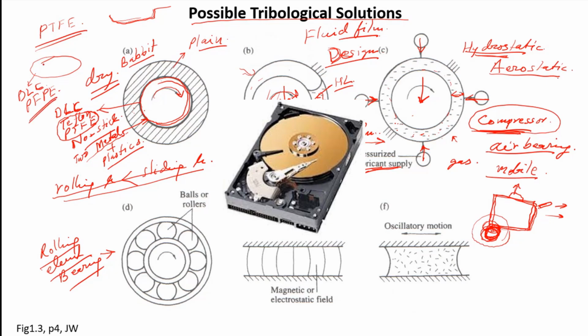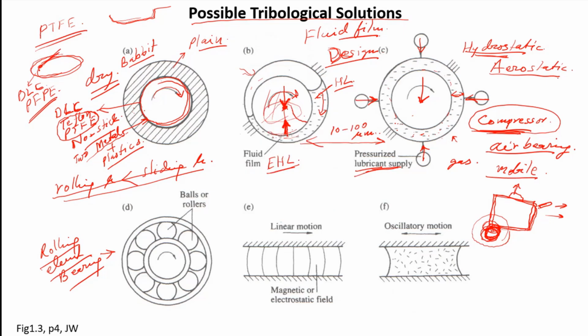another material. In a magnetic hard disk, where we save our data in our computer, there is a disk and there is a slider here. The slider reads and writes the information while the disk rotates. The problem is the tribological interaction, and therefore we use this kind of coating. As we go along, I will give you some more examples of these coatings. In fact, these coatings are applied even in conjunction with fluid film lubrication. So there are many examples, and I will talk about those later.